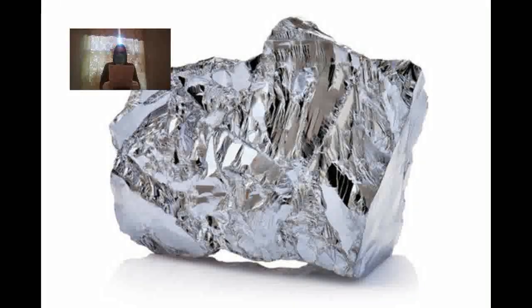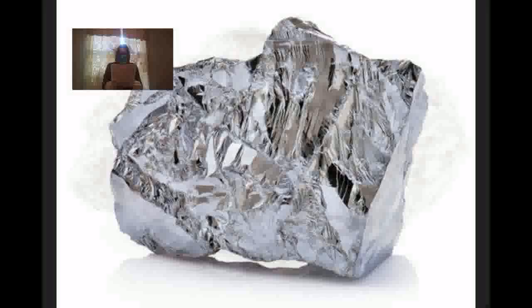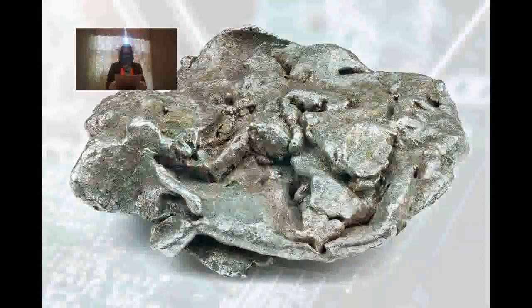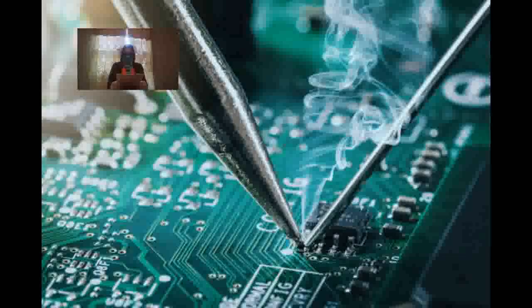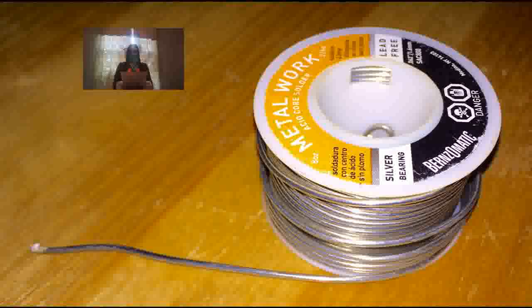The ends of the film resistor serve as the connection terminals and are made from metal such as nickel or silver, or they can be made from an alloy. Solder is used to mount and connect the film resistor to the circuit board. See figure 3-30. The process is very similar to the same process used to manufacture integrated circuits or ICs. The process is covered in more detail in Chapter 19.